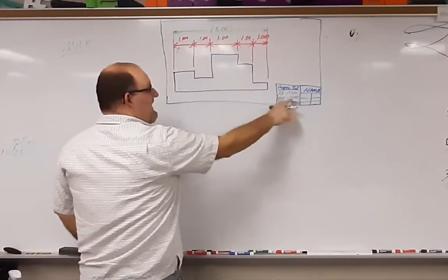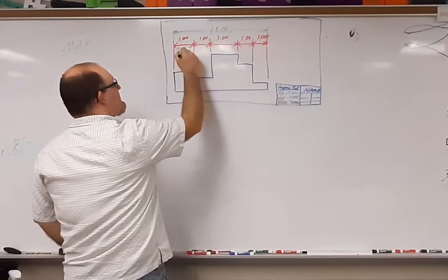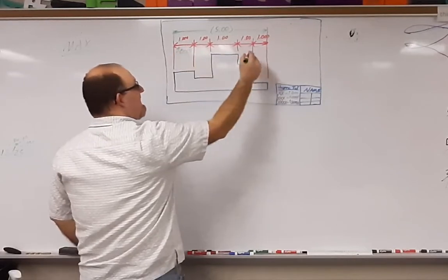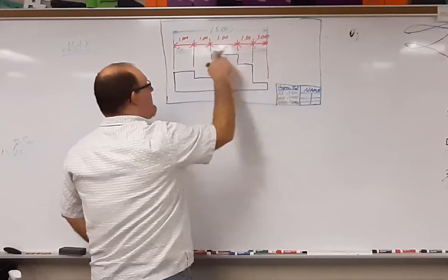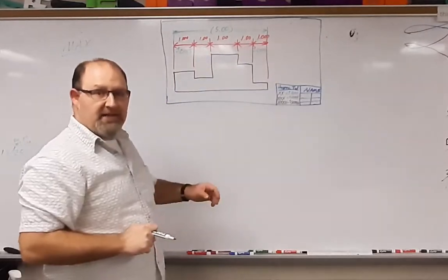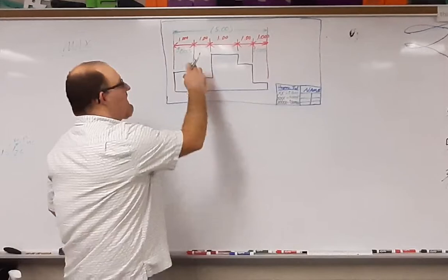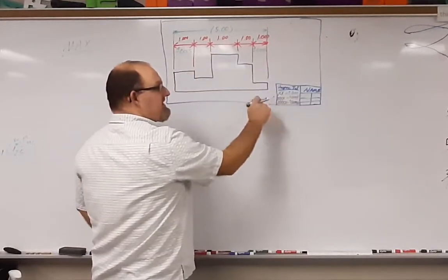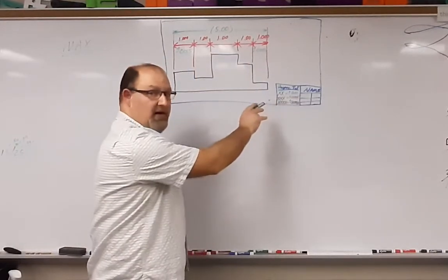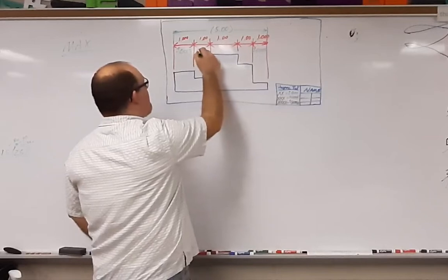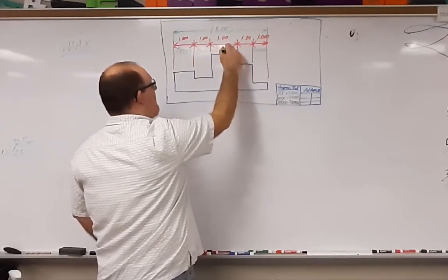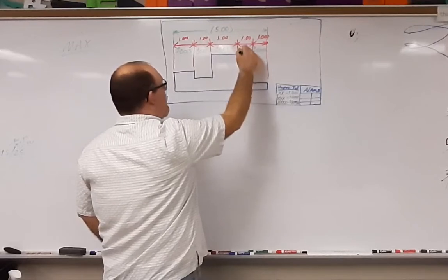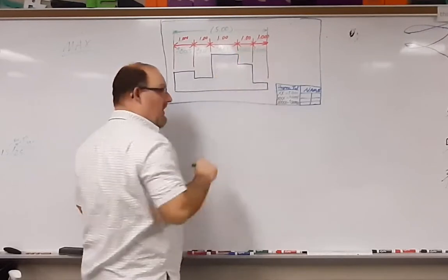This one is a 3-place, so the 3 places plus or minus 0.005 and plus or minus 0.005. So these 2 end ones are plus or minus 5 thousandths. The 3 in the middle are a 2-place decimal, so the 2-place decimal in our unspecified tolerance is plus or minus 0.01, plus or minus 0.01, plus or minus 0.01.